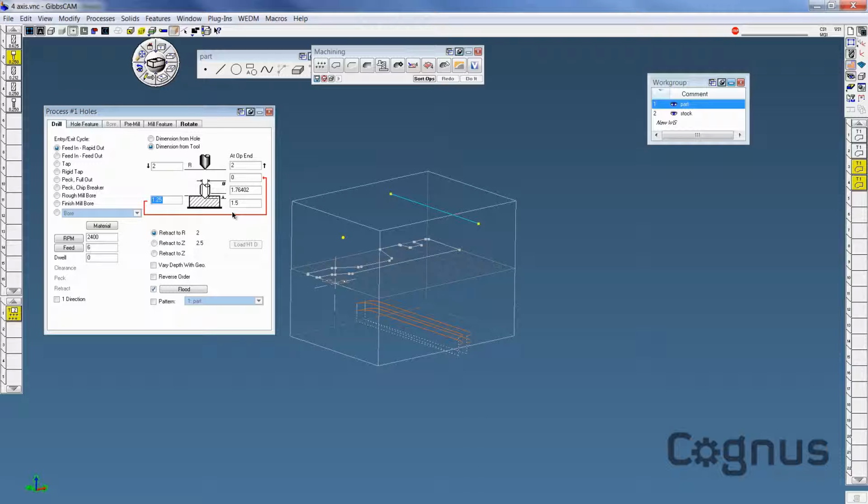There's 3 ways to define depth of a drill. There's tip depth, full diameter depth, and if you don't exceed the diameter of the tool, you can determine the depth of the drill by the spot diameter the tool leaves. That's what we'll do here. I'll leave a spot diameter of 0.2 inch. Let's set our entry-exit values to just above the top Z level, 1.35. We have different retract options. We'll select 1.35. I'll close this off.